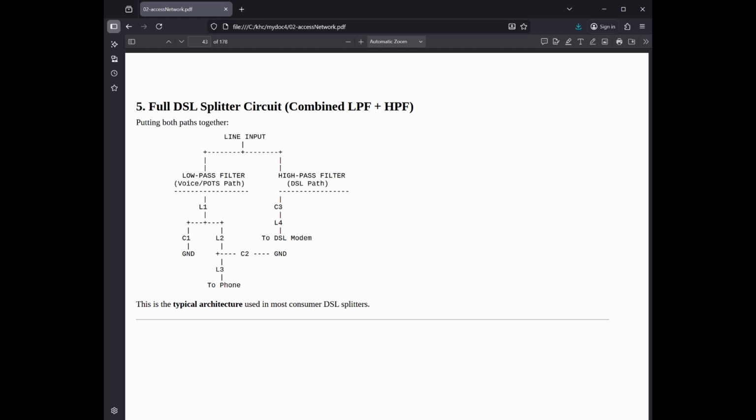2. Basic circuit diagram, schematic. Most commercial DSL splitters use a passive LC (inductor-capacitor) network. A typical high-quality second-order low-pass filter circuit for the phone side is structured as follows: line tip, to DSL modem tip, L1 inductor (example 10-15 mH), to phone tip, C1, R1 matching resistor, to phone ring, L2 inductor, line ring, to DSL modem ring.